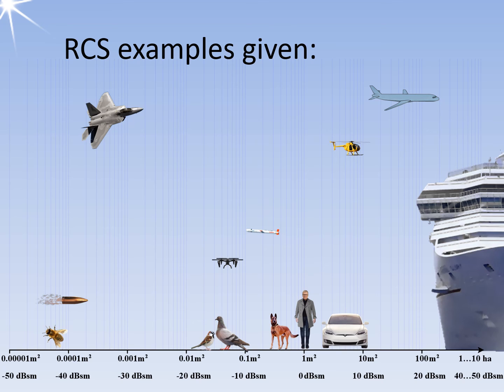The F-22 Raptor fighter aircraft is also up to -33 dBsm in this range. In contrast, a Tomahawk cruise missile would offer a huge area of -3 dBsm. That is as much as a shepherd dog. In between are birds and quadcopters in the -17 to -15 dBsm range.